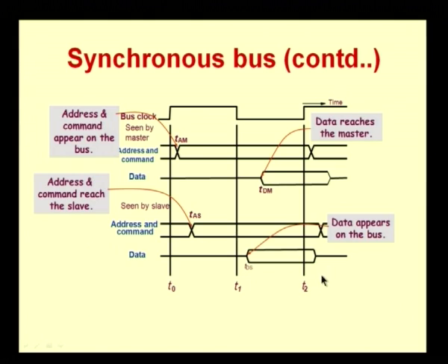So we have the setup time, which is the time before the clock that the data should be there, and the hold time, which is the time after the clock for which the data should be available. Only then can you make sure that the data is successfully written into the buffer. Okay. So these are the things that we need to keep in mind with respect to the timing for the synchronous bus. You can see all these things captured in this figure over here.